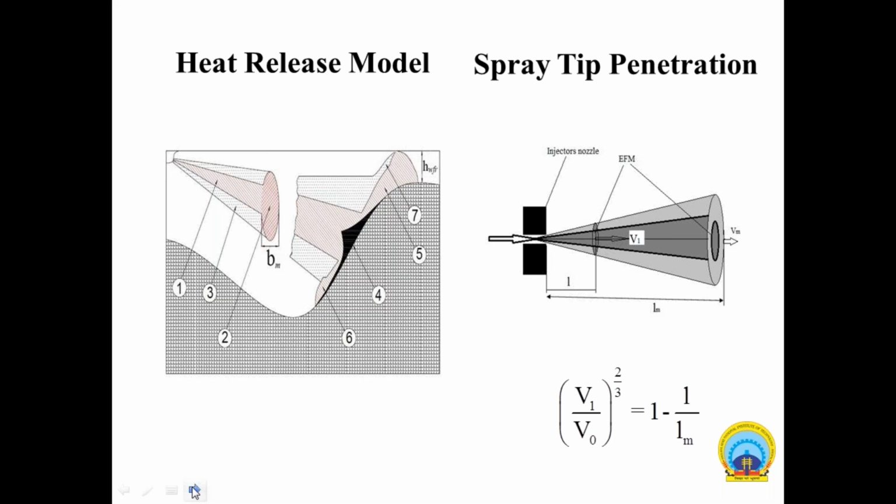The first is the difference of fuel droplet evaporation condition in different spray zones, the fuel redistribution among zones in the process of free spray movement and in its interaction with the wall, then interaction of fuel sprays with the walls of the piston bowl and the possibility of fuel hitting the cylinder liner and the cylinder head surface.